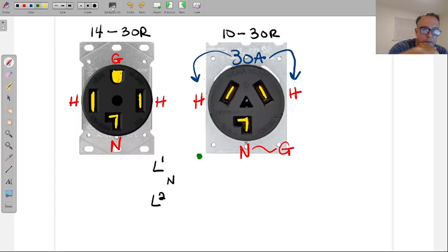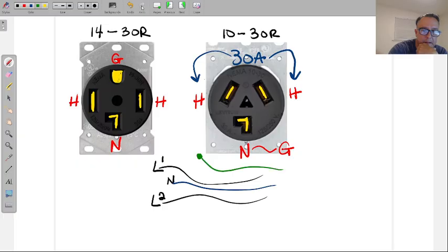So here's what they tell you. Let me put all this back. There's also a little piece of metal that's connected to the neutral and bonded to the frame of the dryer. If you're going to use the 4-wire plug, you have to remove that little clip and leave it like this.